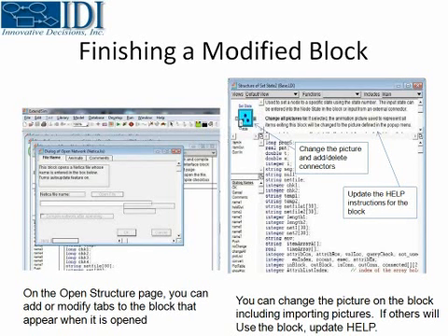One of the things that I did learn kind of the hard way as I was doing this is if you're going to modify an existing ExtendSim block, don't delete any of the input boxes that are on these pages, because if you delete it and then in the code it's looking for a variable in there, it's not going to work. You're going to get an error.